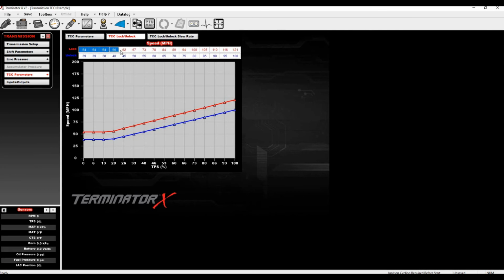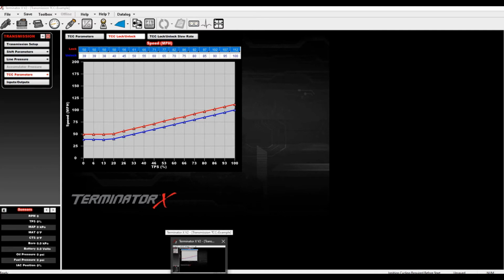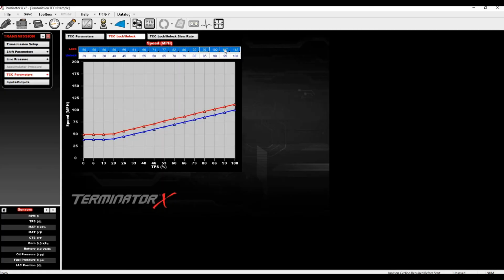So I'm going to grab the whole thing to start with and drop that down. 20% throttle, 50. Okay, we've dropped the whole thing. Now let's look up here at wide open throttle. Let's say I want to grab the converter at 5,500. It's 122. Watch this just work out totally and make me look silly. Okay, all right, look, a little bit different at least.